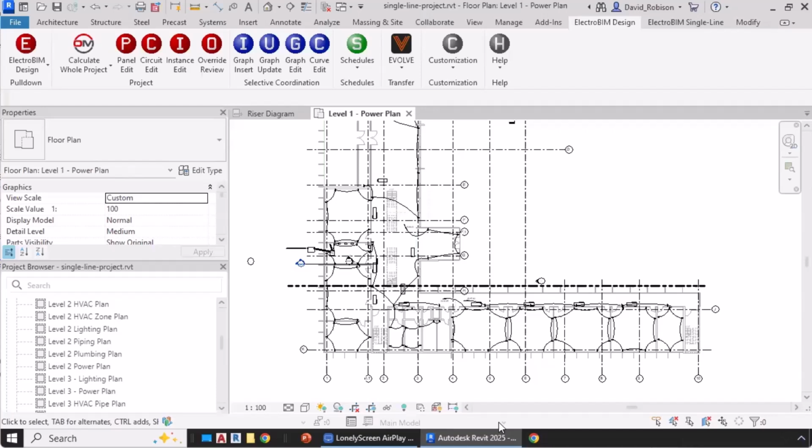We're going to be looking at branch circuit device breaker sizing. There are a couple of different ways that we can size your branch circuits, and we're going to go over all of those in this training. The default is always to size based upon 125% of the connected load. So if you connect a receptacle or a light fixture or a motor, we're going to take a look at that load. We're going to give you a breaker that is 125% of that load.